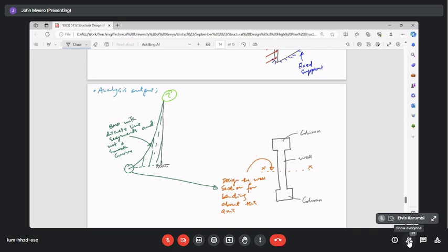Some standards approach the design of the shear wall as sections. So they have an outer section which is designed to take the bulk of the bending, and then the inner section, a portion of the wall that is near the neutral axis, is provided with minimum reinforcement for walls. So if you pick different standards, you find different approaches to how the shear walls are designed.